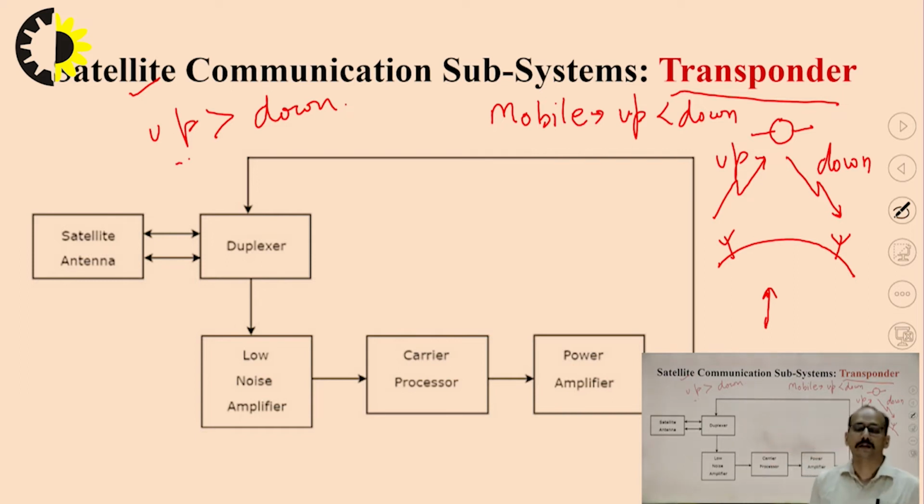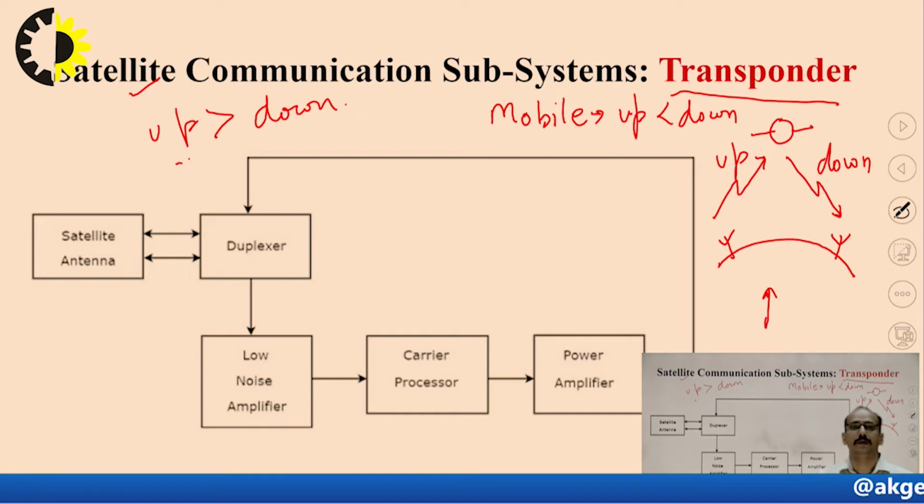The transponder is the main part, a combination of a transmitter and receiver with a processor or processing unit. What the transponder does in the communication subsystem is get the data from the earth station, process it, and resend the data on the downlink frequency to the Earth.